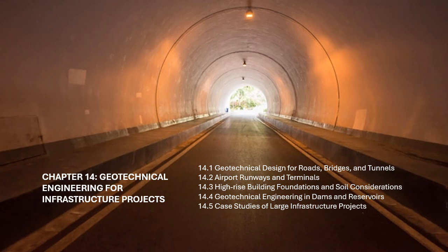4.2.4 Innovations in Geotechnical Design for Airport Infrastructure. Recent advancements in geotechnical engineering are being applied to airport infrastructure projects to enhance performance, sustainability, and efficiency. Geosynthetic reinforcement. The use of geosynthetics, such as geogrids, geotextiles, and geomembranes, has been expanding in airport construction due to their ability to improve soil stabilization, reduce settlement, and enhance drainage.